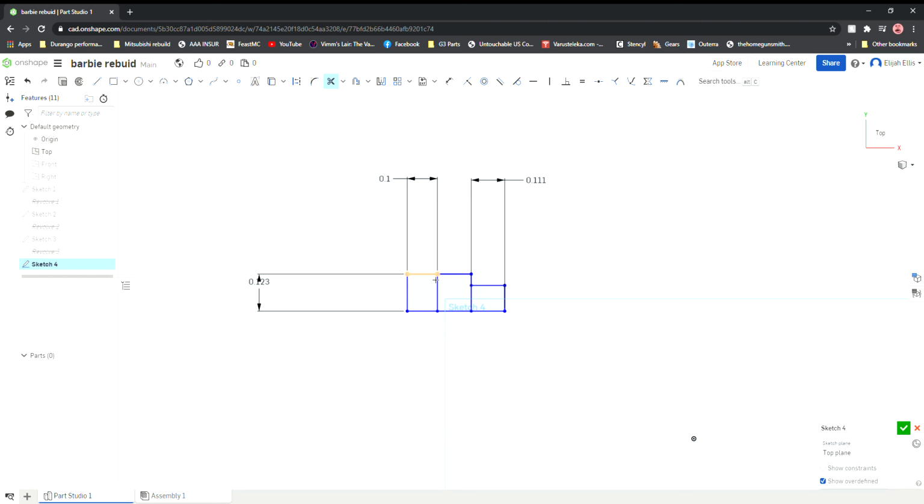Now I also have a large conical shape on here. So let's go ahead and measure that. Give it a bit of a twist to make sure that we're concentric here. Look at that, 0.342. Let's go ahead and see if this will mess with anything, but 0.342 divided by 2, 0.171.